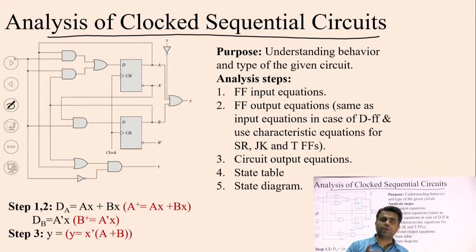In most of the questions we have prepared a circuit as a final answer, but in these kinds of questions, the examiner will be giving us a question and the circuit will already be there, and we will be asked what this circuit is going to perform. That means we have to prepare a state diagram: if this circuit is in this state, if you give 0, it will enter that state, output will be that, and from this state to that state. That means we have to depict the behavior of the circuit from this given circuit, and we have to convert this into a state diagram.